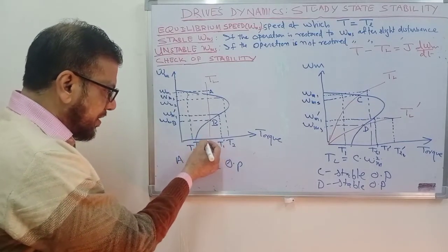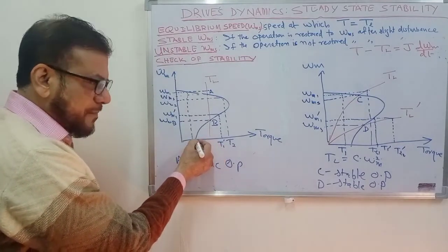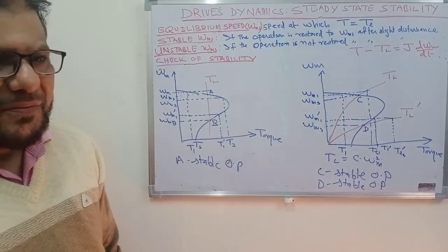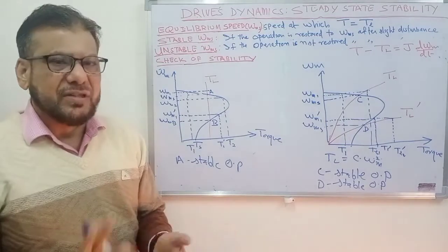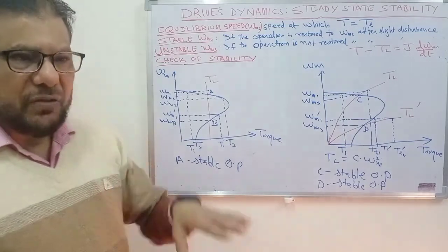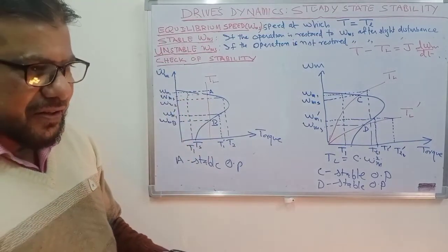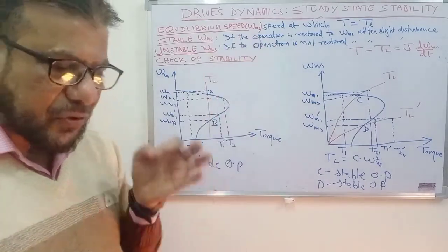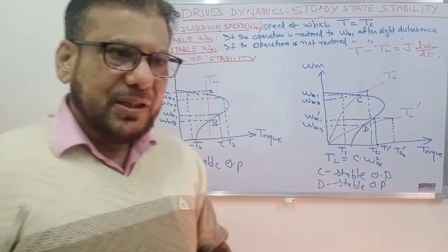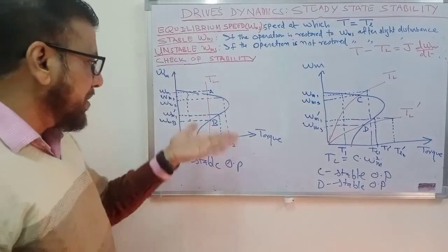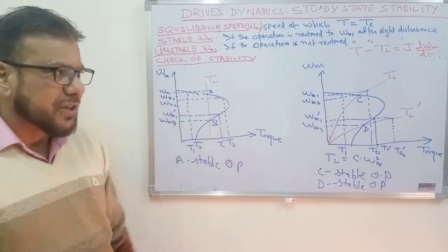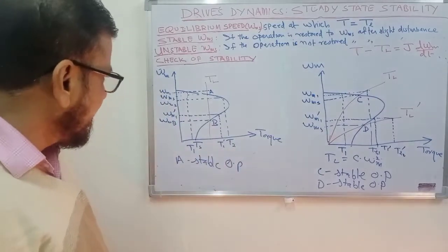This is the load torque. This is the starting torque. Starting torque is less than the load torque. So this means that the motor will not start at all. Motor will remain stationary. It will start drawing heavy current from the source, and if you leave it connected, the motor windings will be overheated and will burn out. So you have to stop the motor immediately if this happens.